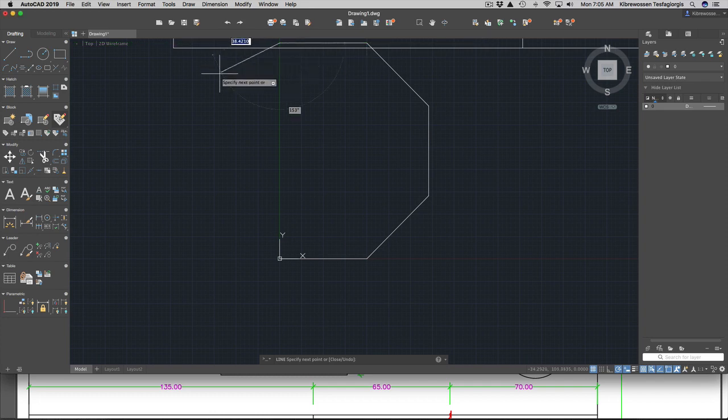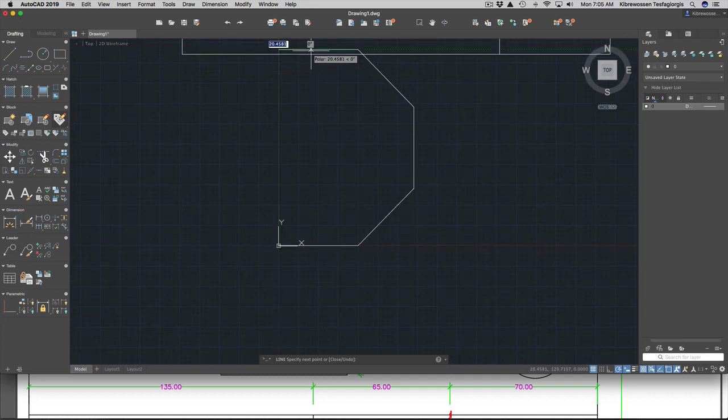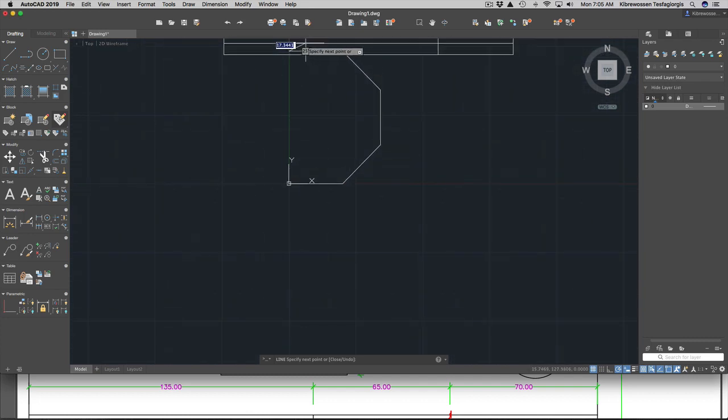Okay, then in this direction I'm going to continue with 50. And then in this direction you can count another 50 dimension, but this time it's going to be 180 plus, because the angle is measured with the horizontal, right? From here, look, the angle starts from 0, goes up to here, and then it can even come here, so it's going to be more than 100.